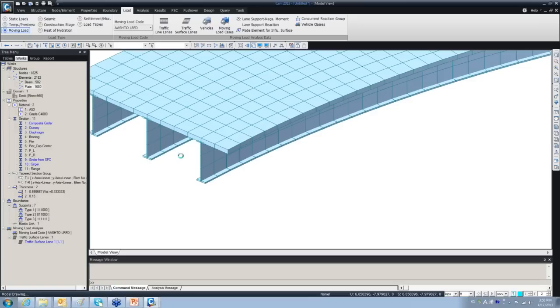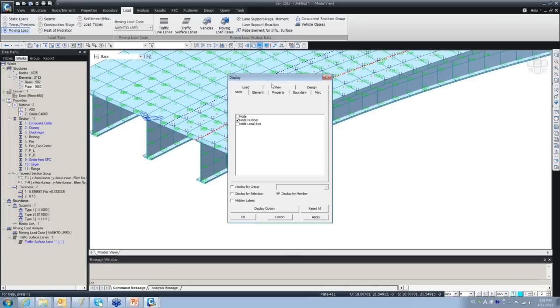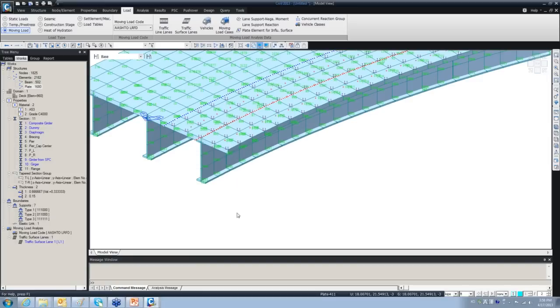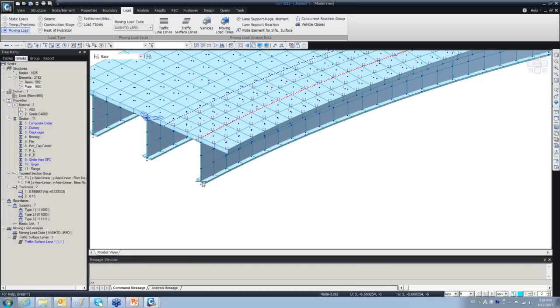this corner right here, if I turn on the node number, you see that there is one node up here, and there is one node up here, one node down here. So I really don't need any additional nodes to be defined there to create those boundaries. Those additional nodes are only used when you are modeling it with the composite section, because this is a one-dimensional element, and then you will need an additional node to be able to go into the space or three-dimensional.